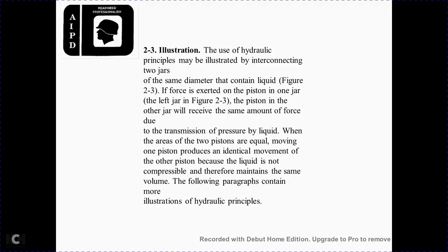2-3 Illustration. The use of the hydraulic principle is illustrated by the interconnection of two jars of the same diameter containing liquid. If force is exerted on the piston of one jar, as in Figure 2-3, the piston of the other jar will receive the same amount of force due to the pressure transmitted by the liquid, because the areas of the two pistons are equal. The movement of one piston produces an equal movement of the other piston, because the liquid is not compressible and therefore maintains the same volume. The following paragraphs contain illustrations of hydraulic principles.